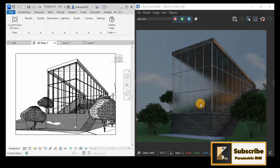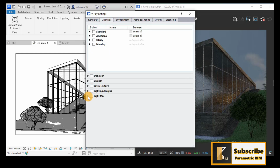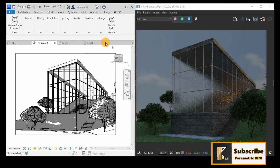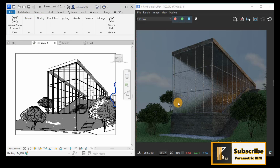In order to see the effects more clearly, you have to go to settings, and then go to the channels, and here we have light mix. I have to click it as a family type and then close this, and I have to render as a production to see the effect more and more clearly in the V-Ray rendering.